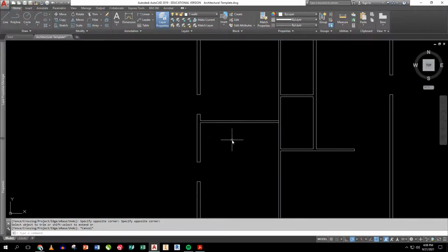Okay, now all I gotta do is offset a few things to get the closet. Well, it's 6'10" across the closet, so I'm gonna go offset 6 foot 10 inches, enter, from here over, enter. I'm gonna go back into offset and do a 3.5 inch wall right here. Okay, and then I'm gonna do a 2 foot closet. Okay, actually it's got 1'10" inside that closet. That's a pretty narrow closet, but okay.